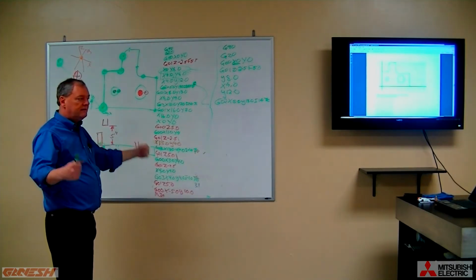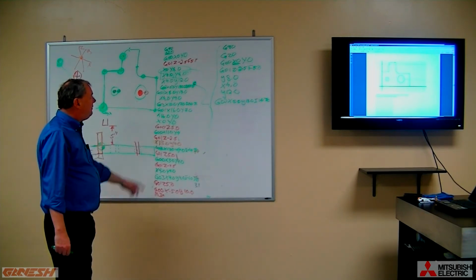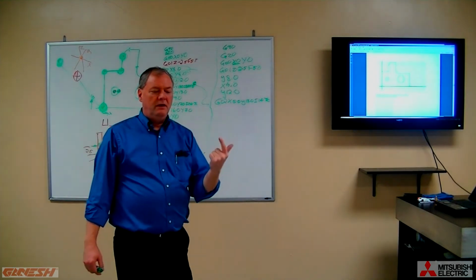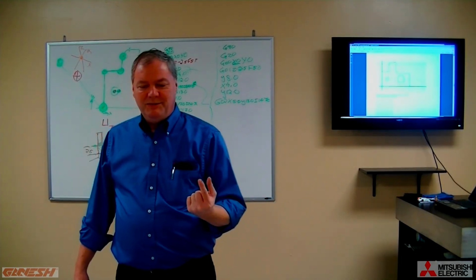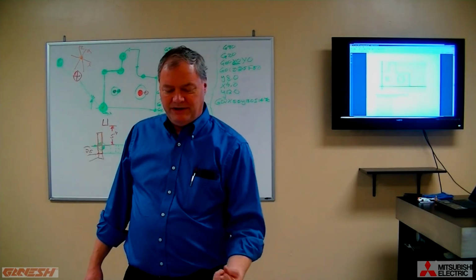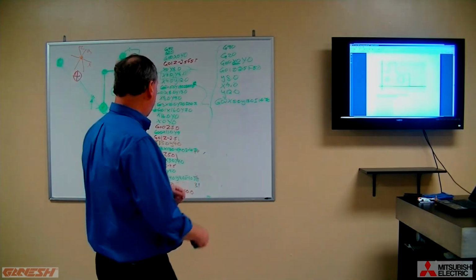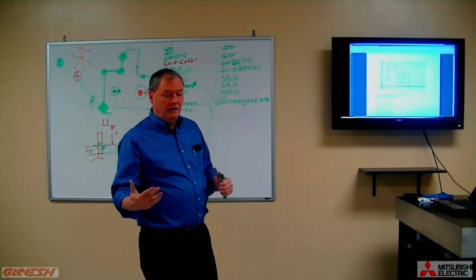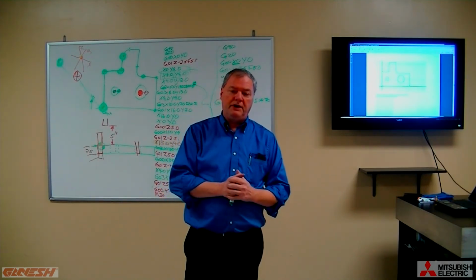It's complete, it's self-contained, and it's ready to go. The only thing we didn't do in this program, if you remember, when we do machining, the spindle has to be turning, right? We can't have a stationary tool and expect it to do profiling around our part. So one of the other things we need to do, we need to turn on a spindle to the appropriate RPM.